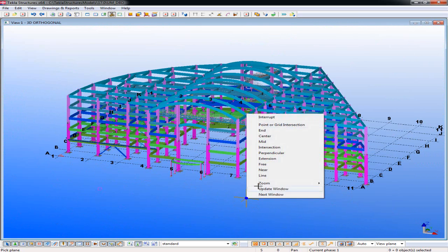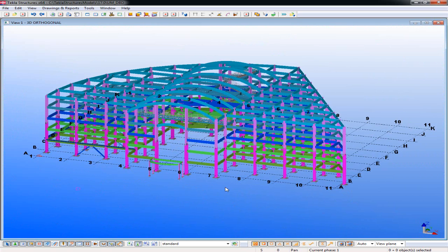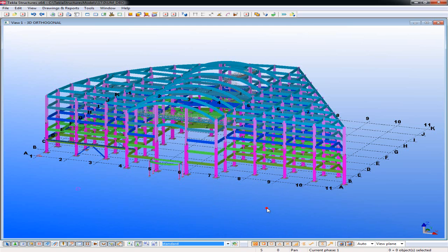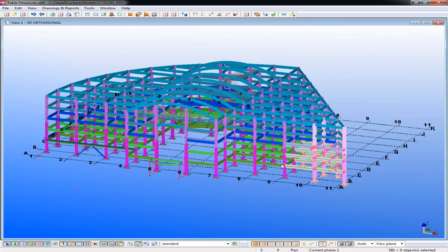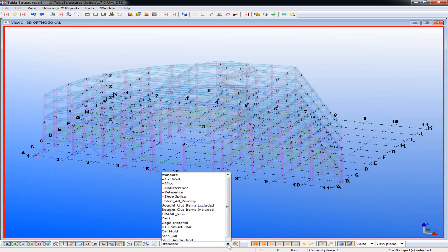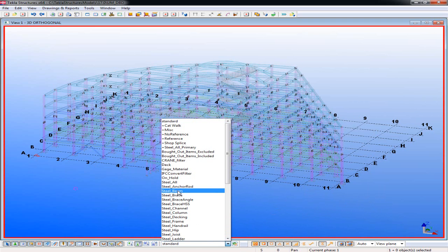and we can talk a little bit about some of the filters. What we have down here, if you look at this toolbar, are just some simple selection filters. If you wanted to refine, zoom in on a particular area and locate maybe just the beams or the columns or whatever. Right now, if I just window select an area, you'll notice it's going to highlight everything within that particular location. But let's say I just wanted to grab, for example, the beams in a location.